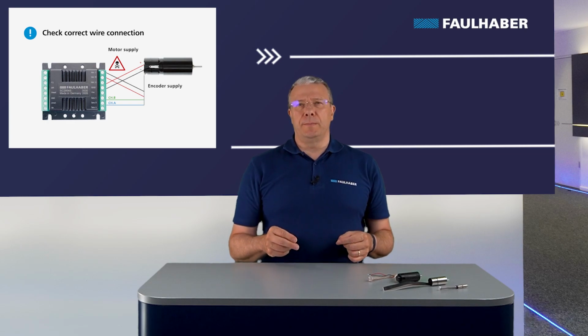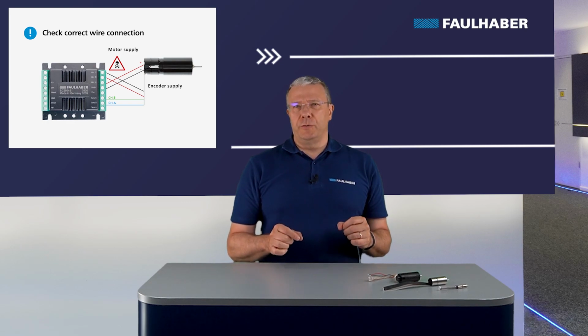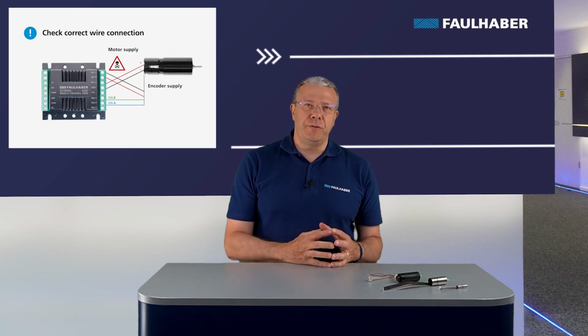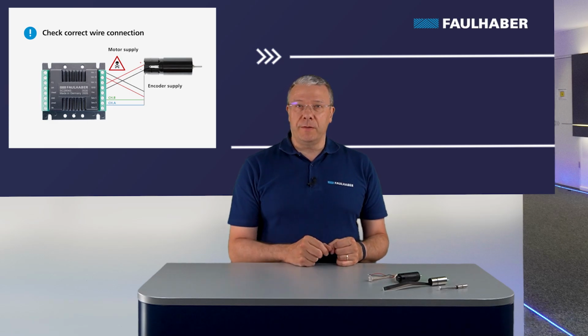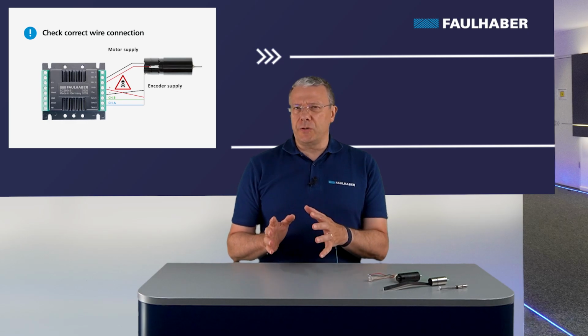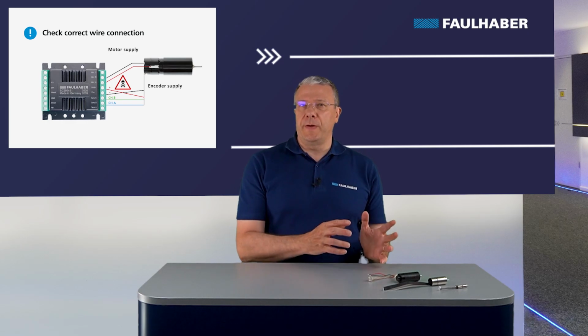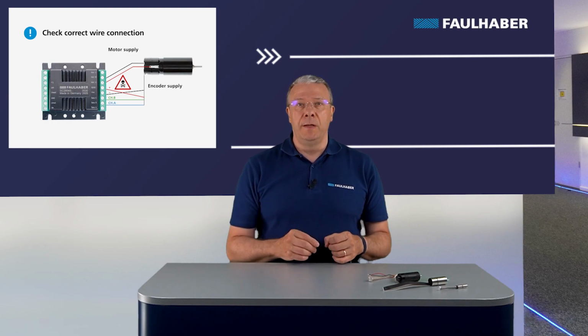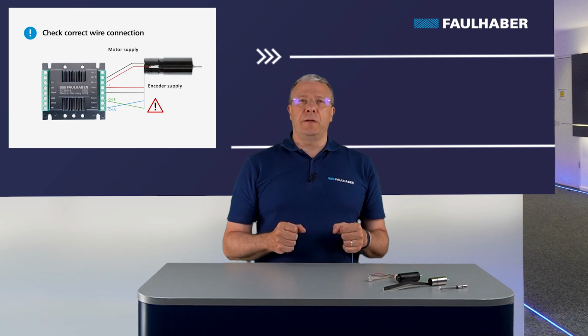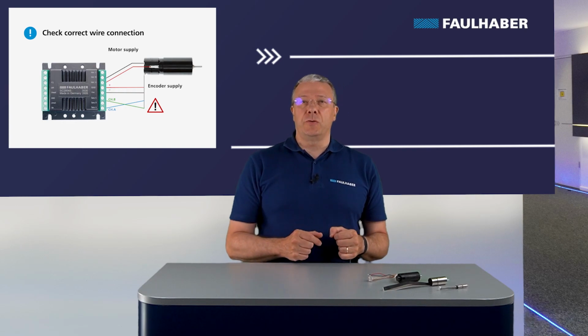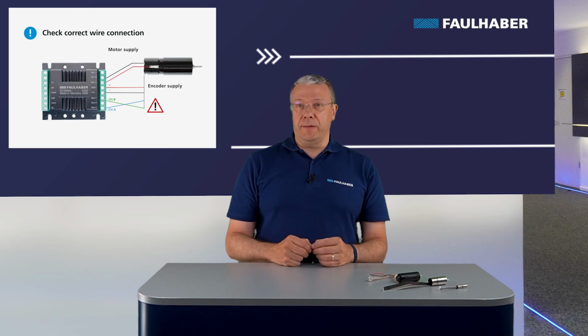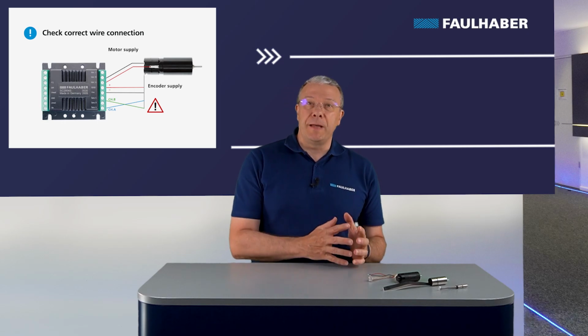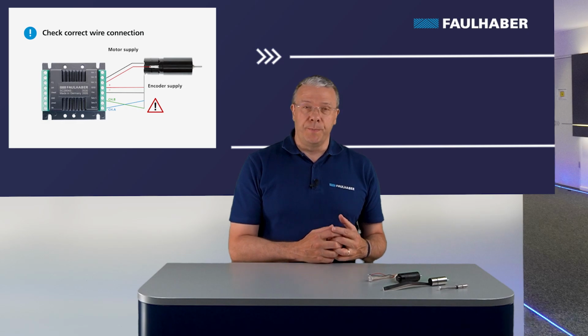Normally, the encoder supply is delivered directly by the drive electronics. In this case, the two supply wires must be correctly connected. A supply polarity inversion will damage the encoder circuitry, so double-check the connection. The direct connection of the encoder wires to the motor phases will damage the encoder because of the high voltage applied to the digital output channel. The inversion of the encoder channel signal, a missing channel connection, or a short circuit on the channel wires can also cause bad motor control and potential damage.